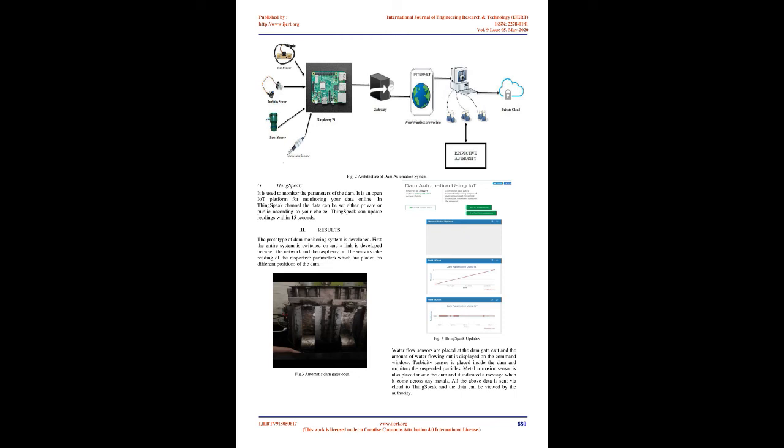B. Turbidity sensor. The turbidity of the water is measured by the turbidity sensor using the principle of optics. It uses an infrared tube by which the transmittance and scattering rate of the water is calculated. The output is calculated by the corresponding voltage value, and it is inversely proportional to the turbidity. Fig 1. Flow chart of the proposed system.